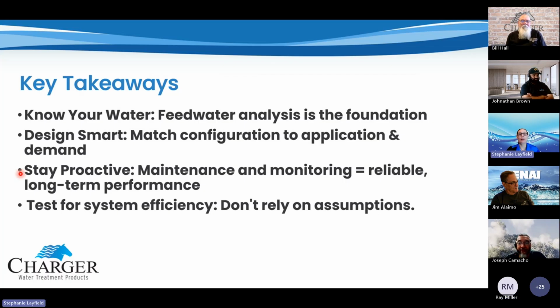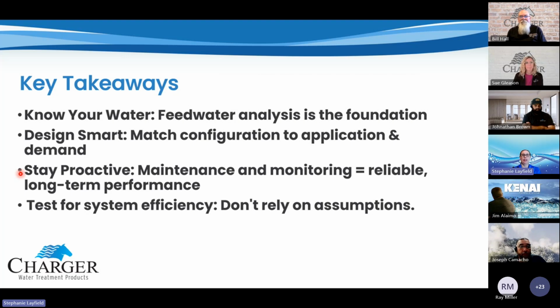Yeah, as a recap, know your water. What are you starting with? What's the water source? Full water analysis. Design smart. What are you trying to get to? What are the customer's needs? What is the area logistics? So design it smart so that it meets your application and demand so that your customer's happy.